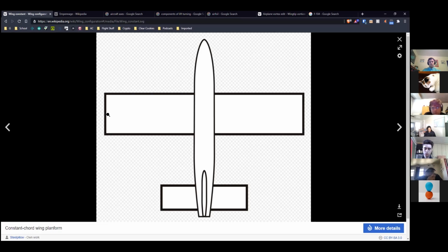And so you generally will have a constant thickness in a wing like this, and that means that your structure here, if you just have the same structure running all the way down, which you don't have to, there's other ways to vary it, but in general, you would have an overbuilt structure. You would have to build the structure here strong enough to hold the whole thing. And if it's the same all the way down, then the structure here is way stronger than it needs to be, which means you have excess weight.